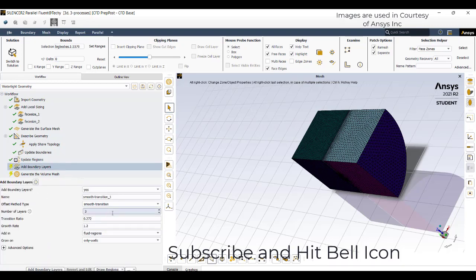In the boundary layers we have different methods, such as first layer height or aspect ratio. Aspect ratio is the length to width ratio. If the length is a higher value compared to the width, then the refinement will be much more. So if the aspect ratio number is huge, say 5, the boundary layer will have a nominal thickness. If you increase the number, the boundary layer thickness will decrease. If you go to 30, the boundary layer thickness on the first layer height will be much lower.